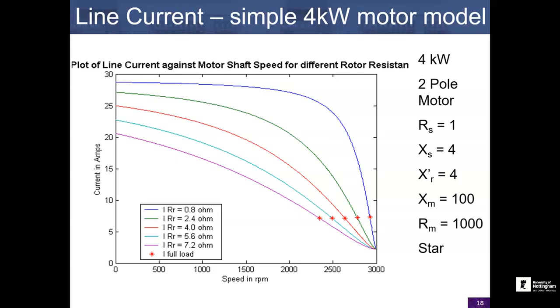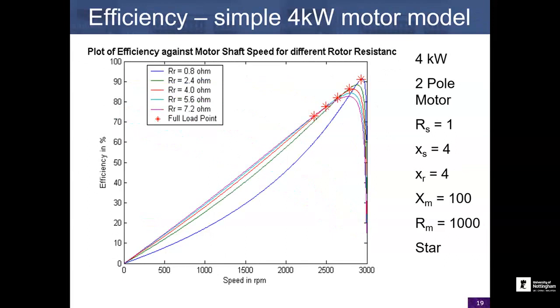So although we'd like to design a machine with as low rotor resistance as possible for operation's sake, sometimes this type of machine won't start or it would trip its supply. And then we highlighted these in terms of efficiency, how that low rotor resistance fundamentally leads to a lower slip operating point, and that gives us less rotor losses and a more efficient machine.